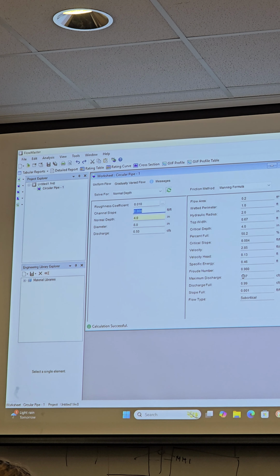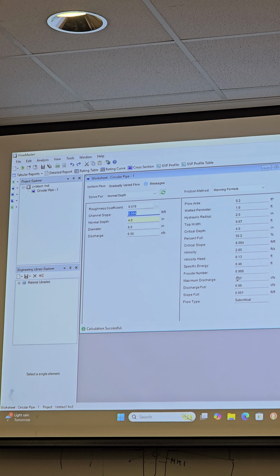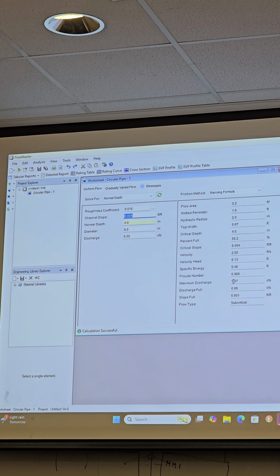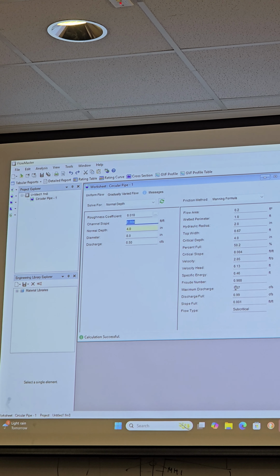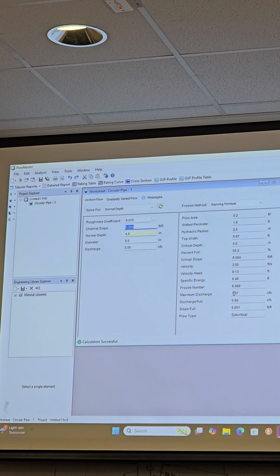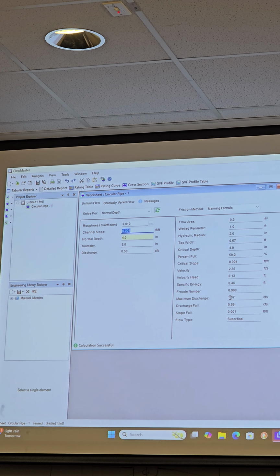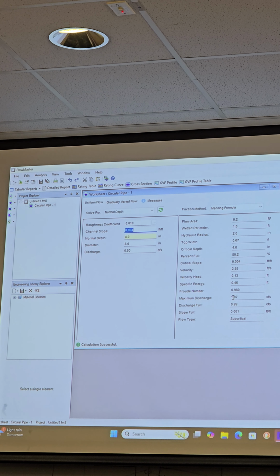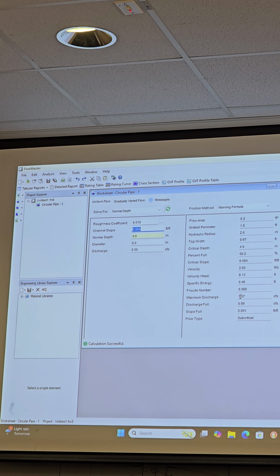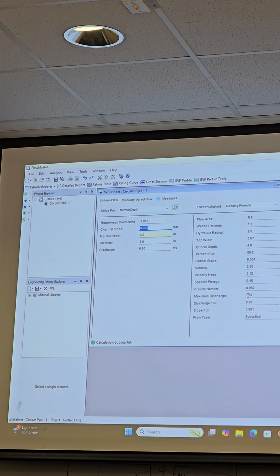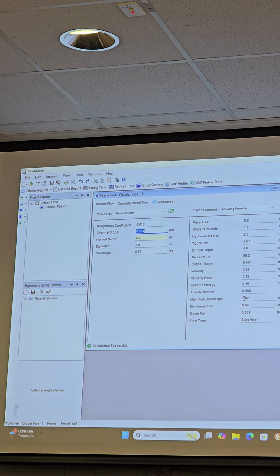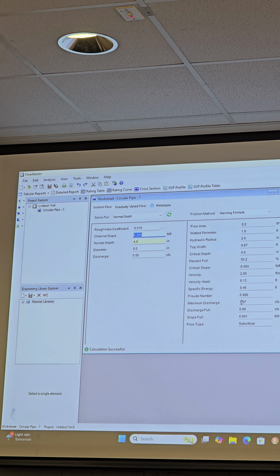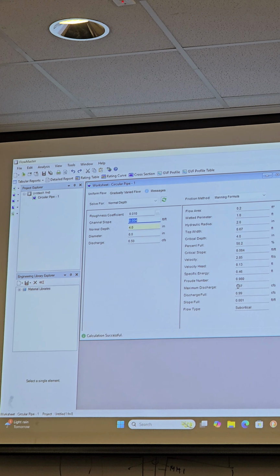So what you're going to do is you're going to do Flowmaster for each of those pipe segments between the manholes, estimate your depth, fill out that table that I showed you over to the right, and check that pipe size. If your depth, just to keep it simple, exceeds 6 inches for an 8-inch pipe, then you need to think about using a bigger pipe. So the goal here is you're going to analyze each of those segments, do the hydraulics, calculate your depth, and then check to see if that 8-inch pipe is an appropriate size.